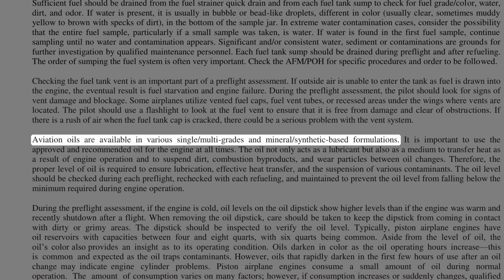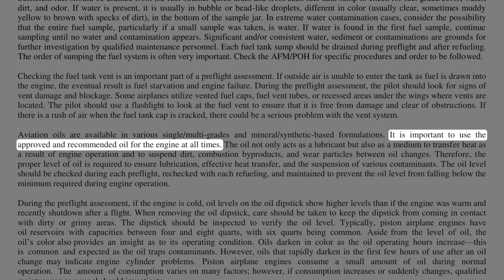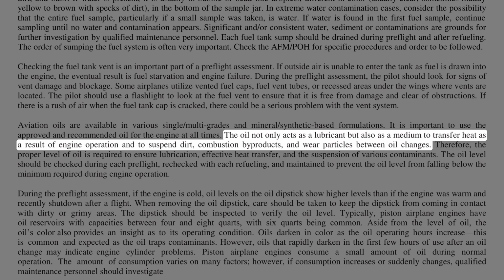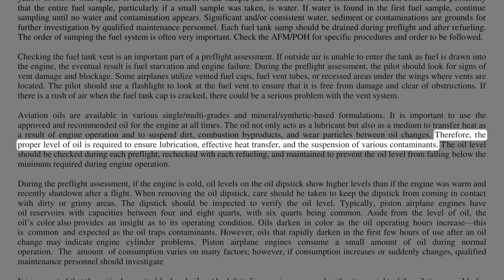Aviation oils are available in various single, multi-grades and mineral, synthetic-based formulations. It is important to use the approved and recommended oil for the engine at all times. The oil not only acts as a lubricant but also as a medium to transfer heat as a result of engine operation and to suspend dirt, combustion byproducts, and wear particles between oil changes. Therefore, the proper level of oil is required to ensure lubrication, effective heat transfer, and the suspension of various contaminants.